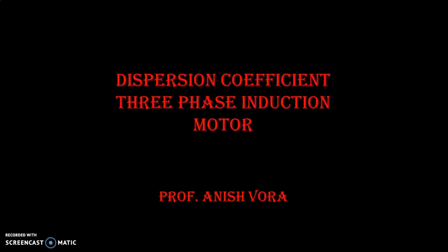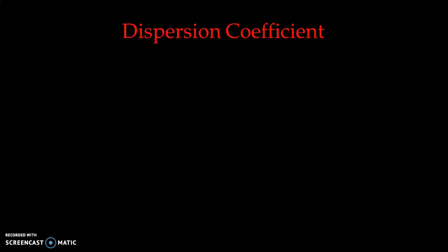In this video lecture, we will study the dispersion coefficient for the three-phase induction motor. In the case of a three-phase induction motor, the dispersion coefficient is very significant because some of the performance parameters, like power factor, overload capacity of the machine, and maximum output, all depend on the dispersion coefficient. So the dispersion coefficient is very important.